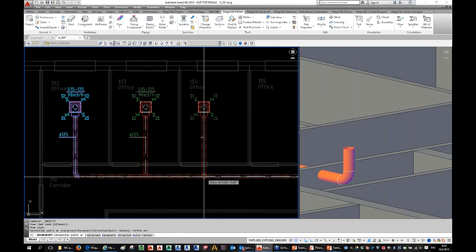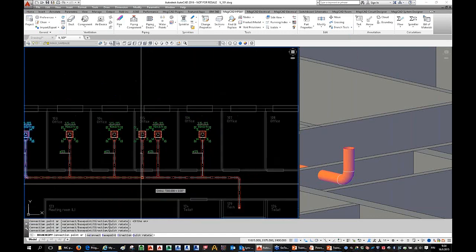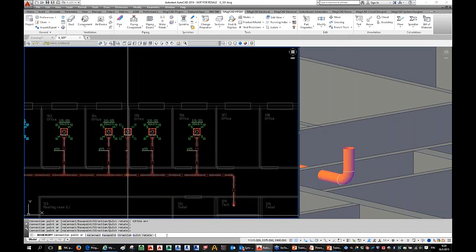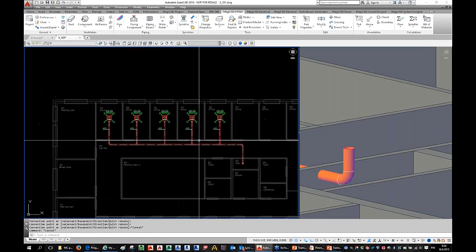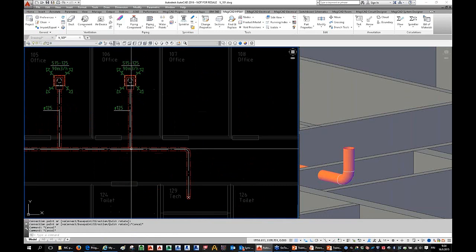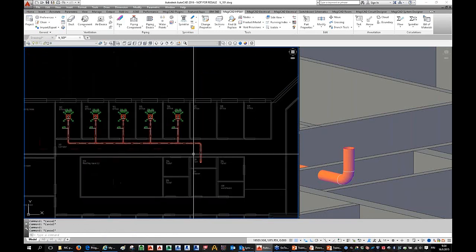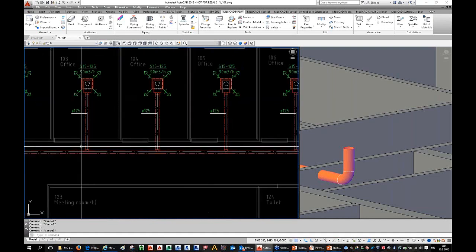and then just click here, like this. I can even give the length to here. So if I want to copy this branch, for example, to 2 meters, 4 meters, I can just write the number there. But as you can see now, it automatically connected the ducts after copying. And now I use outlets, so it uses outlets. If I had used D branches, this would be a D branch.